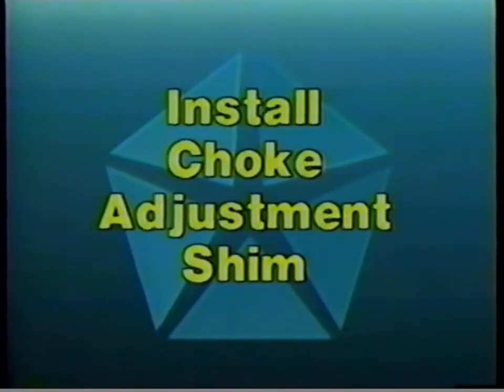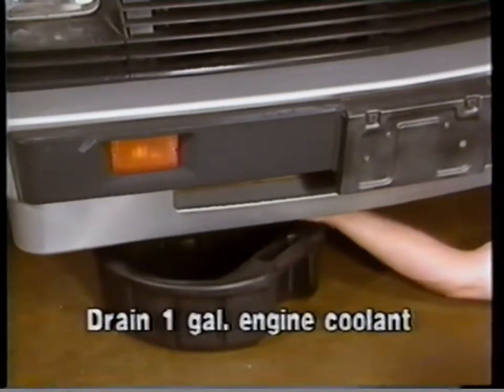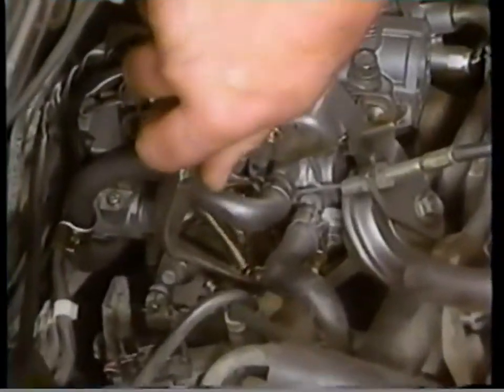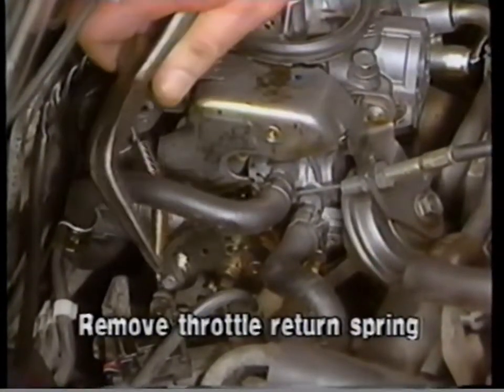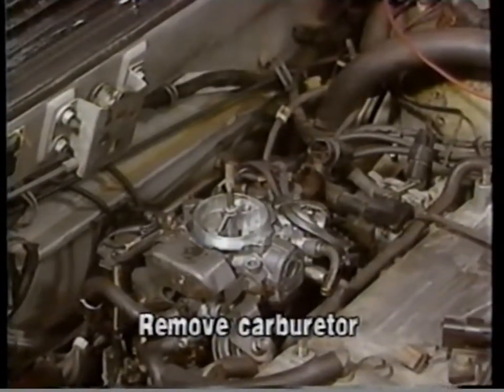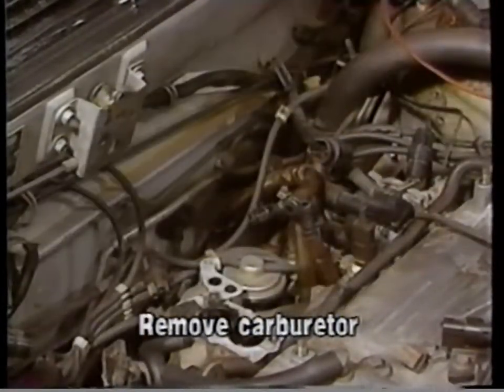The next step in this service procedure involves the installation of a carburetor choke adjustment shim. To do this, first drain about 1 gallon of engine coolant from the radiator and save it for later reuse. Next, disconnect the throttle return spring from the carburetor throttle linkage. Now remove the carburetor by following the applicable service manual procedures and drain any remaining gasoline from the carburetor in a suitable container.